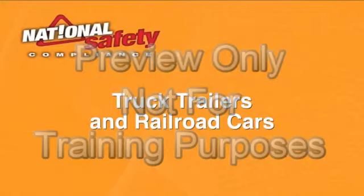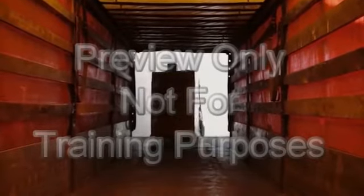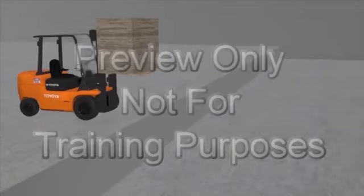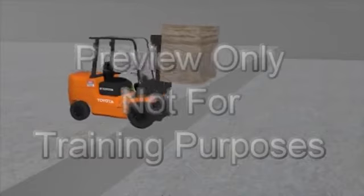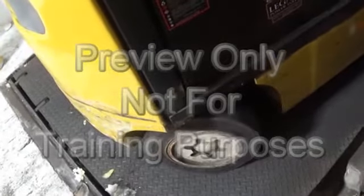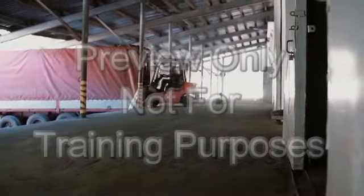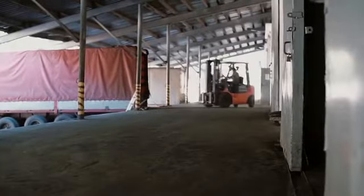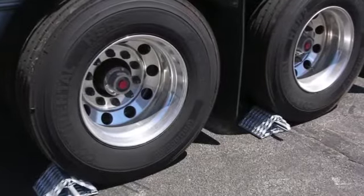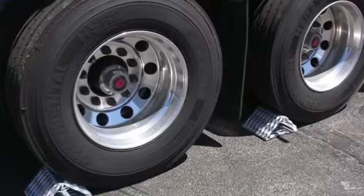Truck trailers and railroad cars. Driving forklifts into and out of truck trailers or railroad cars can be very dangerous. Operators should be aware of situations such as falling off a loading dock and slipping or inadequate dock boards. Additionally, trucks, trailers, or railroad cars can move during loading and unloading. Prior to loading or unloading, make sure to set brakes and block wheels of trucks, trailers, or railroad cars.